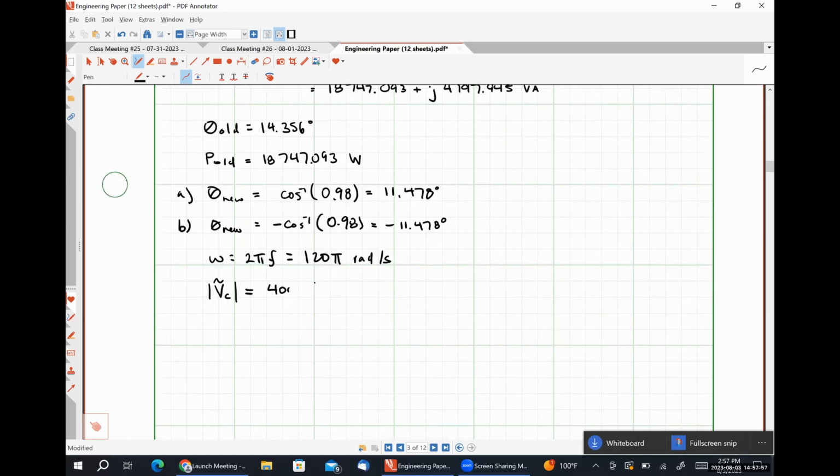The 400 would be like how high that sine wave goes, and then the angle is at which angle it kind of deviates from its origin. Is that kind of how you think about it? Yeah, well, yes and no. The reason I'm saying yes and no is because we're dealing with an effective value. So this is the DC voltage that would give us the exact same average power as an AC signal that is the square root of 2 times the magnitude of this voltage. Okay, so it's like a representation. Yes, exactly what it described. Okay, got it.